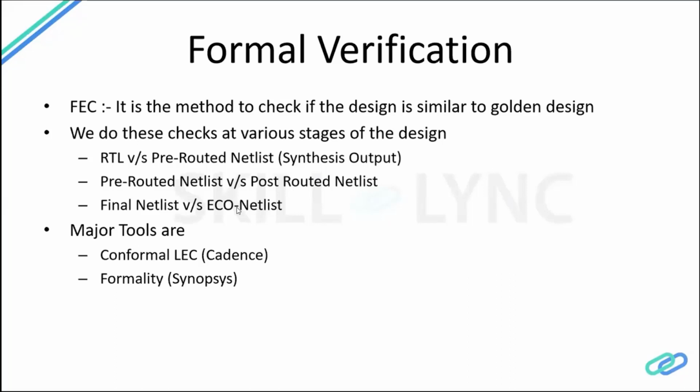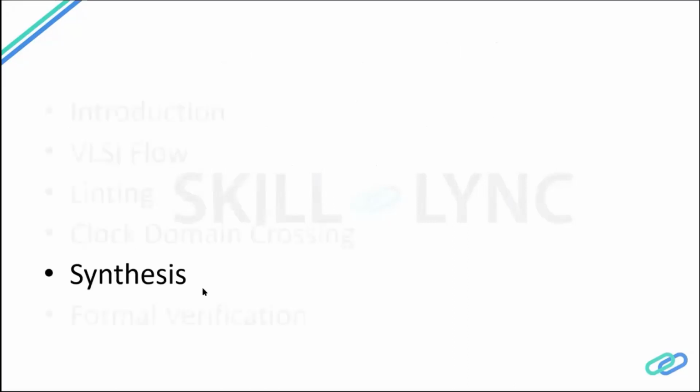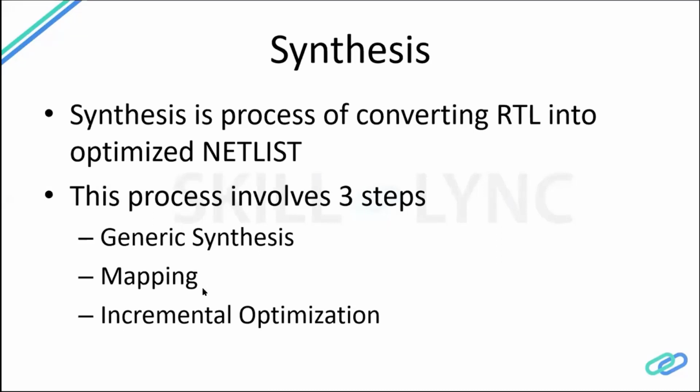And major tools in this formal verification are Conformal LEC, logic equivalence check, and Formality. So these are from the companies Cadence and Synopsys. Now we'll go to the topic called synthesis. So basically, synthesis is converting the RTL into an optimized netlist.